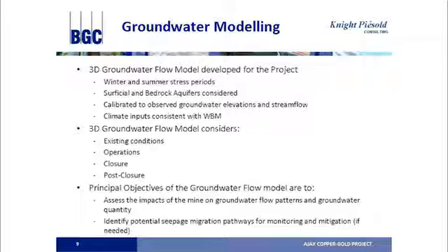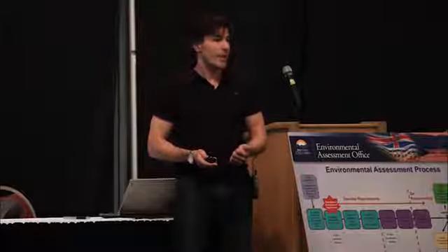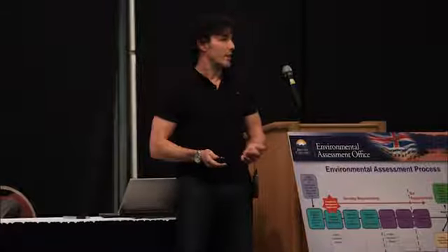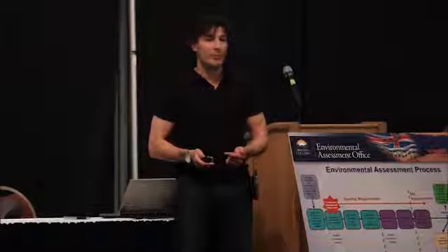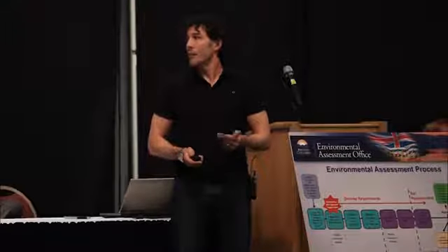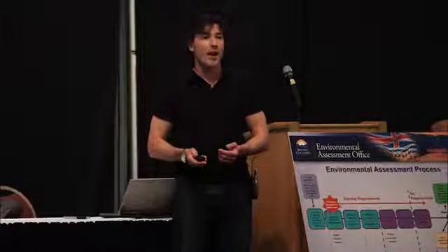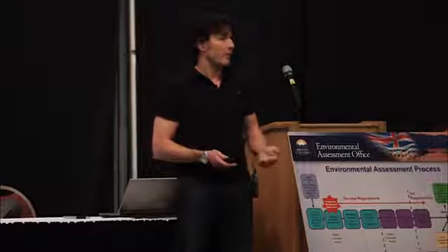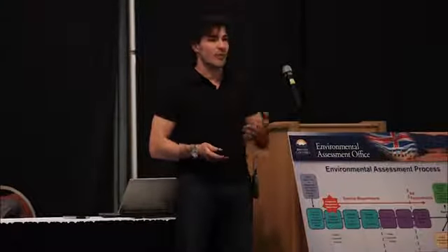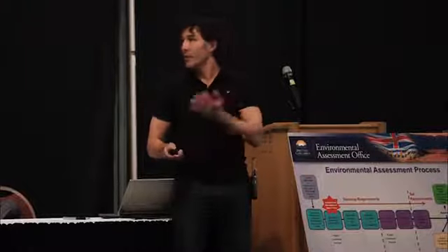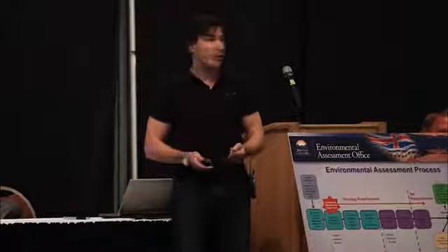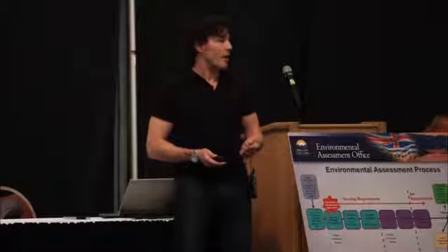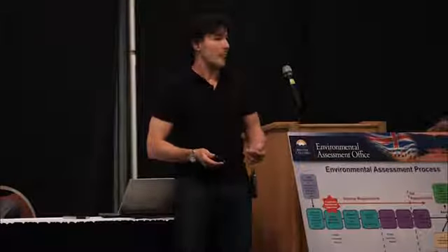So we'll calibrate to measured groundwater levels in the area. That's some of the wells that we saw on the larger map, as well as to a site monitoring network that will be developed as part of the study. Then we'll simulate the mine infrastructure in the model. So we'll put on the waste rock facilities, we'll put in the tailings storage facility, we'll excavate an open pit through operations, and we'll evaluate how groundwater flow patterns might change during the operational period of the mine.